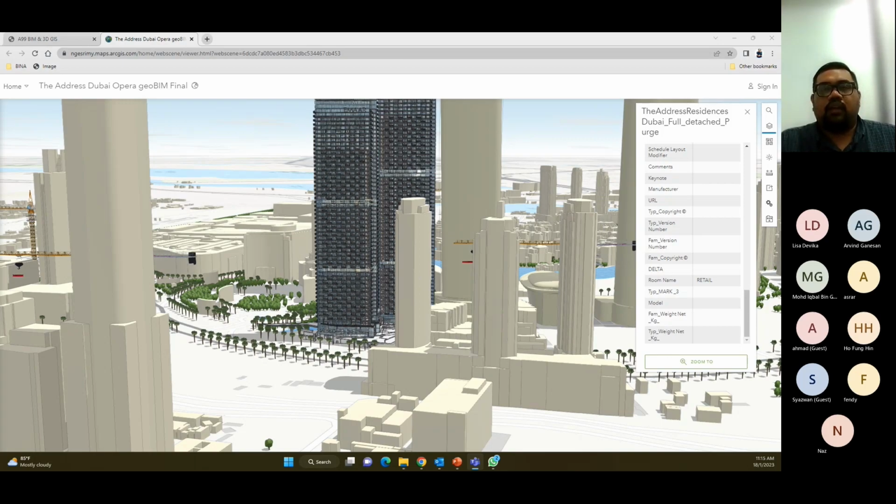Okay. But I think try to avoid it. Try to plan. So for example, if you want to go for one zone, make it 2 weeks before zone A starts work, you need the zone A digital model to be completed first. You do it like that. If not, basically your BIM coordinator needs to go to site daily, basically. But try to avoid it.